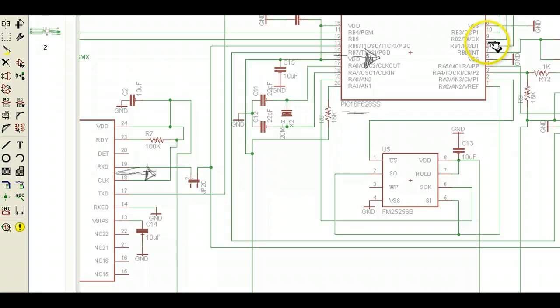And out of this chip comes TTL data in ASCII format. So binary data comes in over here, and AX.25, KISS mode data comes out over here, which goes to the main USART port on our satellite COM board.